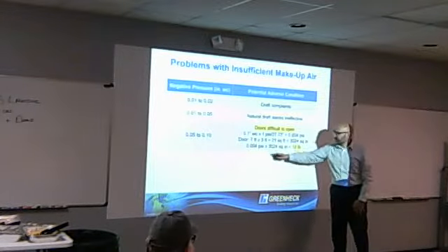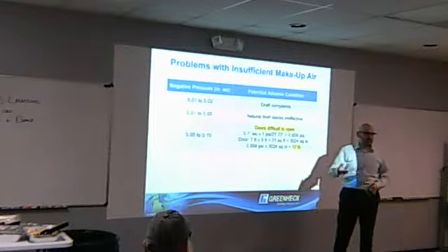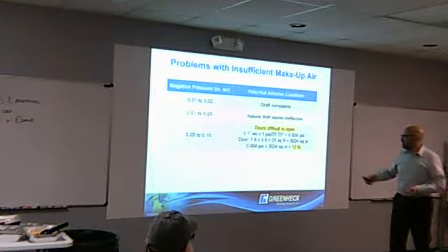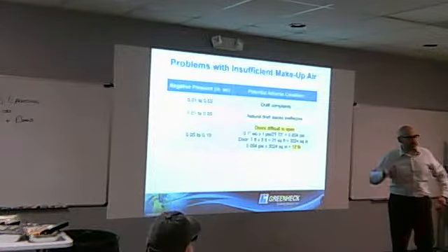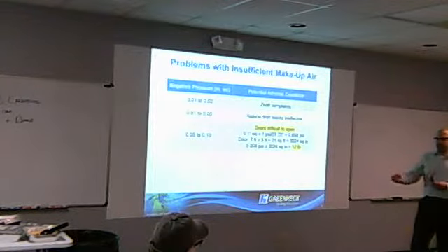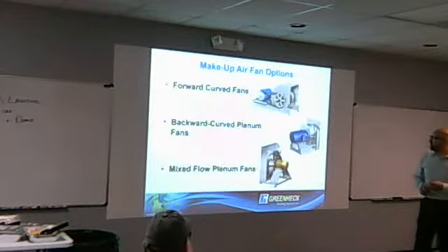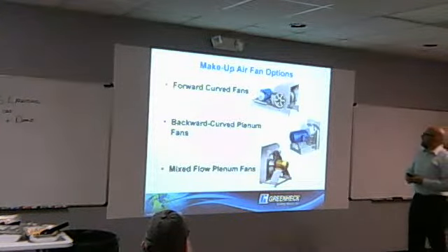So a short, quick calculation. It's about 12 pounds, or just 0.1 inches of water column difference, that you're having to pull on that door. And that's just a 7 foot by 3 foot door. The door could be bigger and the pressure could be more, but you know, it takes some effort to do that. 12 pounds.